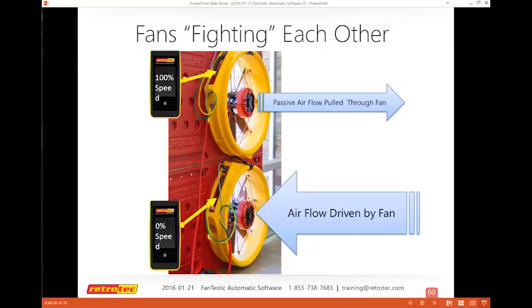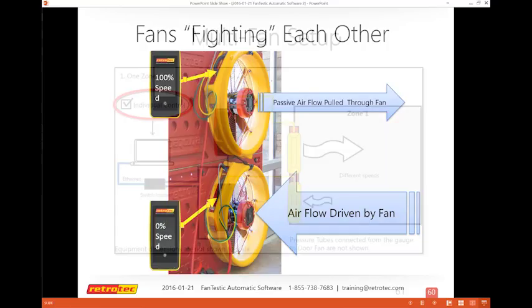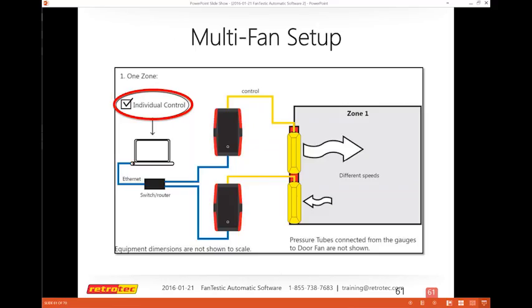And here you can conceive just from the scenario that one fan starts much sooner than the other, and it can actually be going negative. It can be drawing more air out backwards, the wrong way, than what you started. These are some slides that I brought up when Colin started to talk, and these are individually controlled, individually wired, and one fan can actually overpower the other. It's not that uncommon that it takes anywhere from 30 seconds to a couple minutes, and the other one begins to slow down and can go backwards.